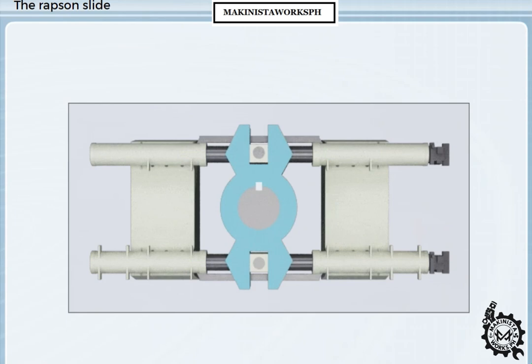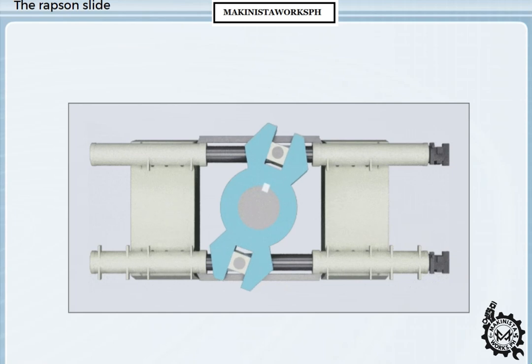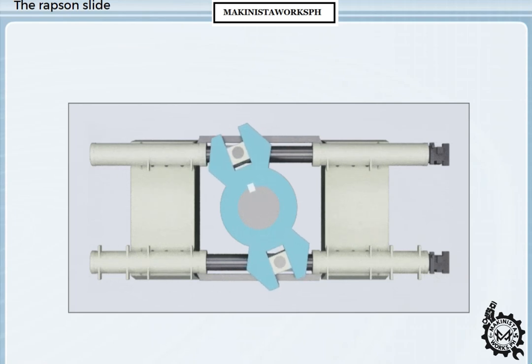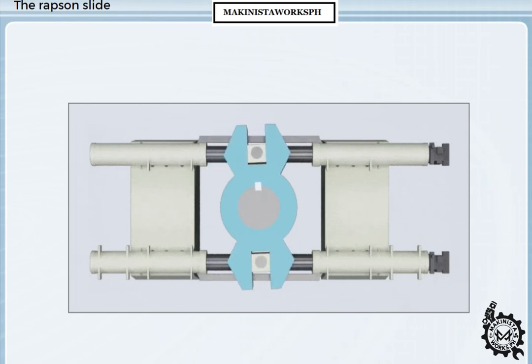Each set of two opposing ram cylinders is connected by a guide bar, which the crosshead guide swivel blocks slide along. The guide bar ensures that no sideways force is transmitted back to the rams, which could cause them to bend and damage the gland packing, leading to leakage of hydraulic fluid. The guide bar can sometimes be designed to include the steering gear stops to limit the maximum travel of the steering gear and rudder, and may sometimes be designed to lock the rudder in position, either in an emergency or for maintenance.